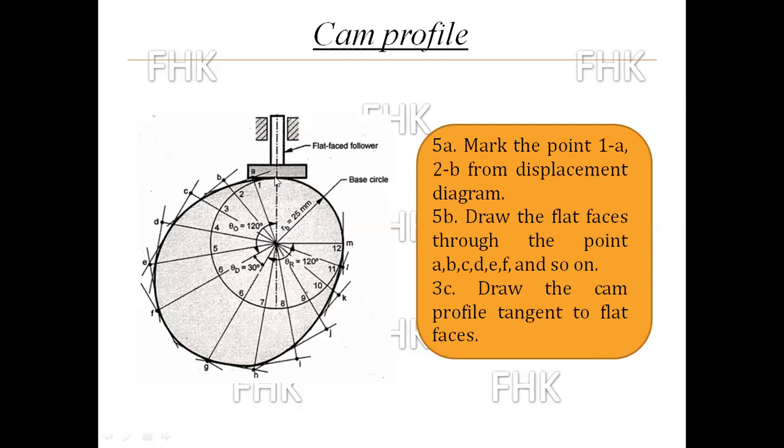Okay, draw the cam profile tangent to the flat face, not from points A, B, C, D, E, F. This is wrong.